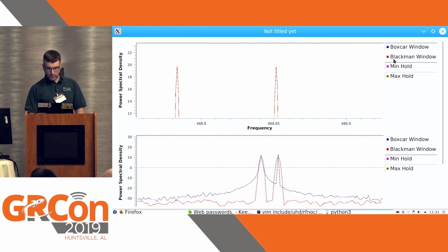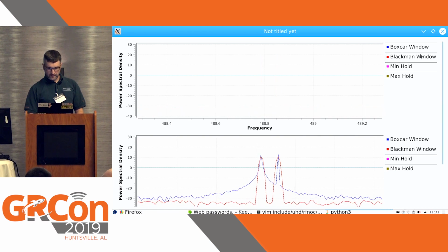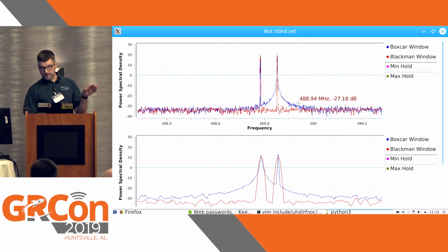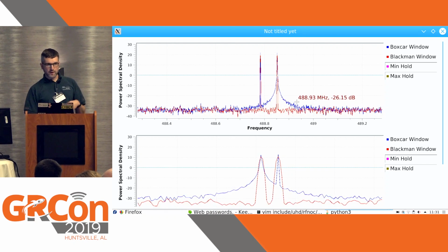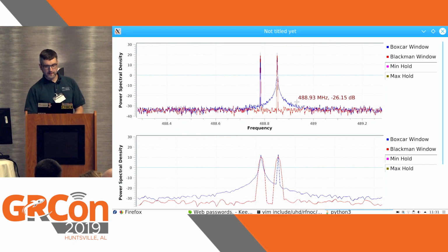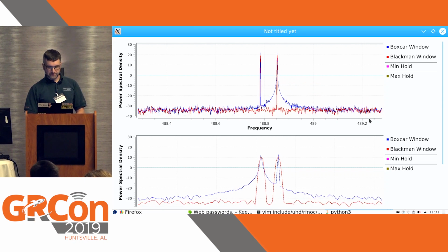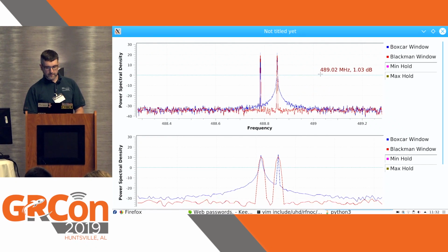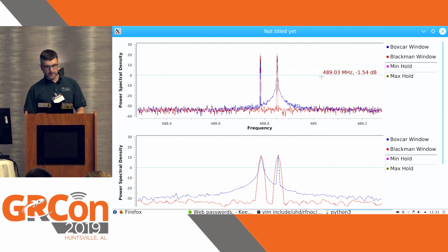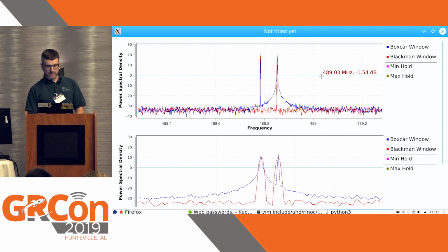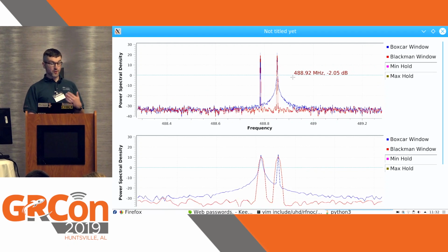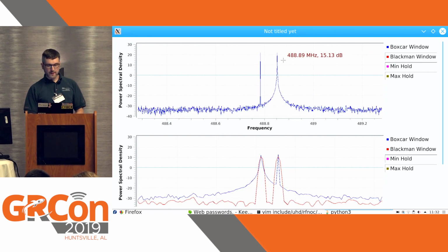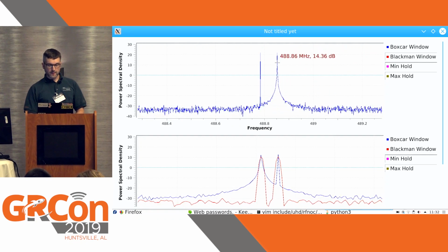And then finally, what is all of this here? Oh, sorry, I kind of skirted over that at the beginning. Before calculating our FFTs, we can multiply our signal with window functions. And that also matters. A window function is basically a time domain function that we apply to our signal first. If we don't apply a window, which we do not here in this case, you will see these side lobes.